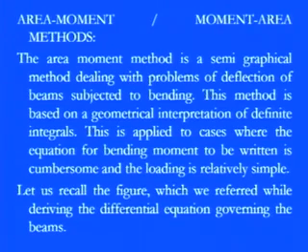If any kind of beam is there, simply supported or cantilever, and any loading is there, we need to focus on the reactions and the load application, that is, the boundary conditions. Once you draw the bending moment diagram, you have a clear feeling that these are the portions where the maximum bending moments are, these are the portions where the minimum bending moments are, and based on the area under that particular diagram, we can calculate the deflection.